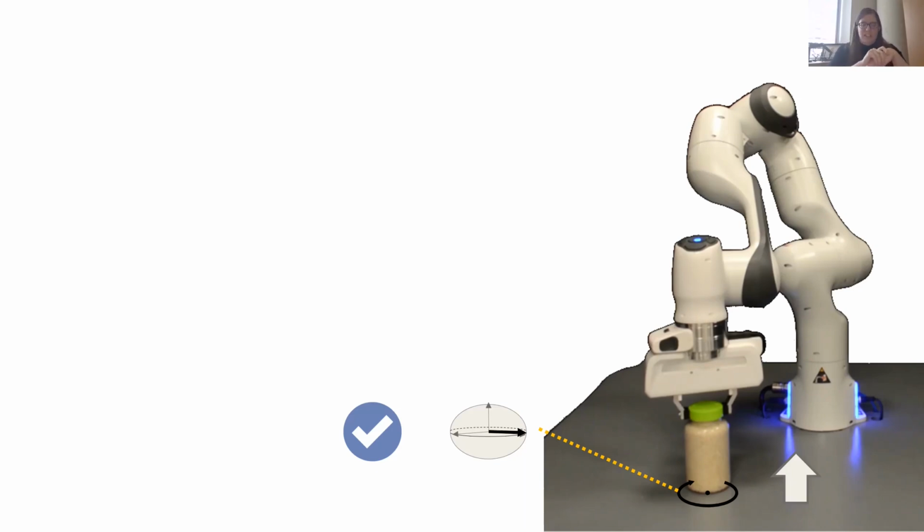Do we want to trust this? Do we actually want to use this frictional contact? I would argue no, because I would argue that it's incredibly brittle and that you're dependent on a very particular value of your friction coefficient, in this case, which you should never depend on a particular value of your friction coefficient.